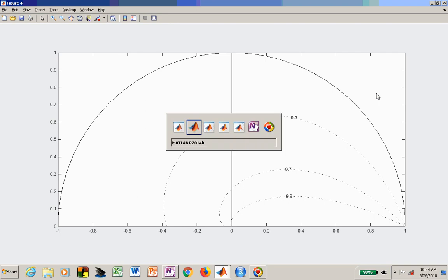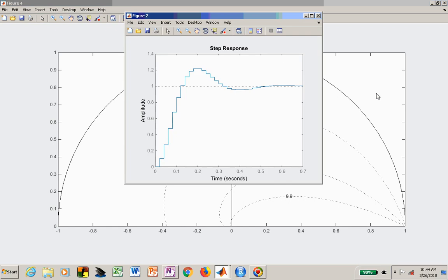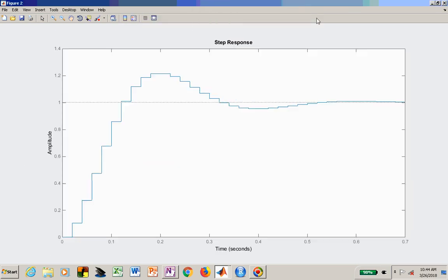And we also were able to, by looking at figure 2, verify or validate our design transfer function with a peak time of 0.2 and a 1% settling time of 0.6 in a second order system. And you can see that we do have a 1 sample period delay between when we apply the input at the origin and when we actually see it at the output.